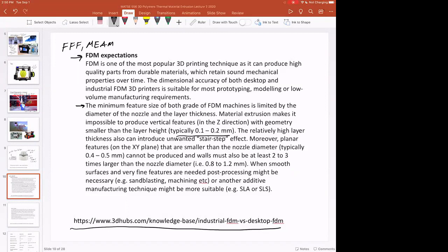And so we'll talk a lot about these characteristic dimensions and how they're matched to the process, whether it's powder bed fusion and the size of the powder really impacts what your resolution is, or whether it's stereolithography that uses liquids, or polyjet that uses liquids, and so we have a different resolution. But now we can connect our understanding of the process and the process parameters to what the part starts to look like, and it mentions it here.